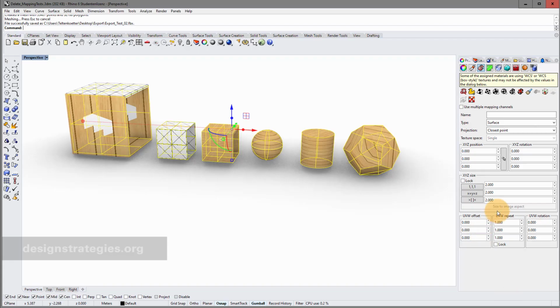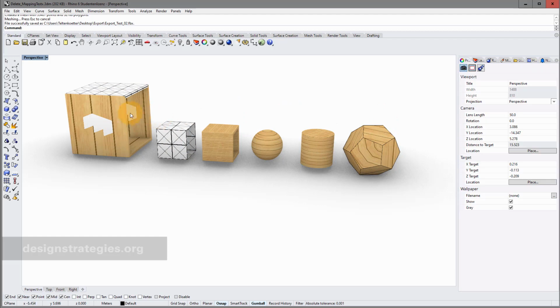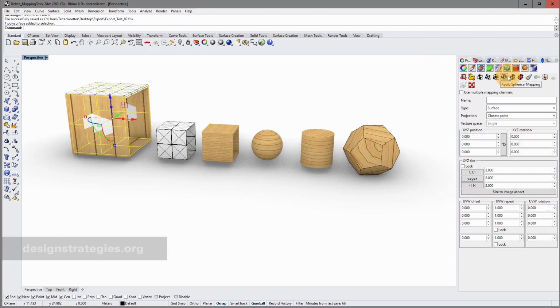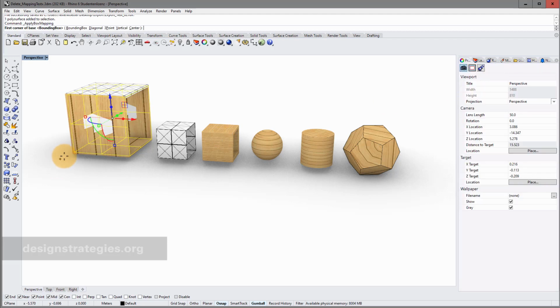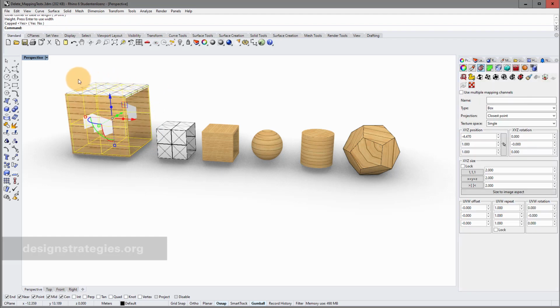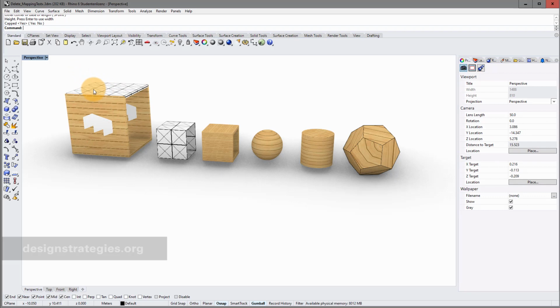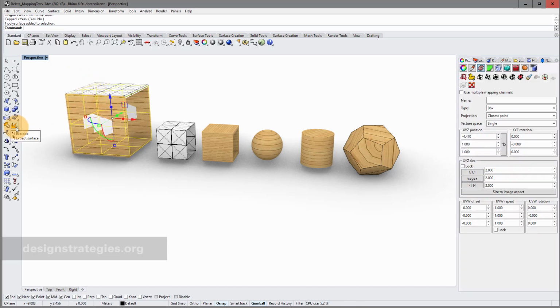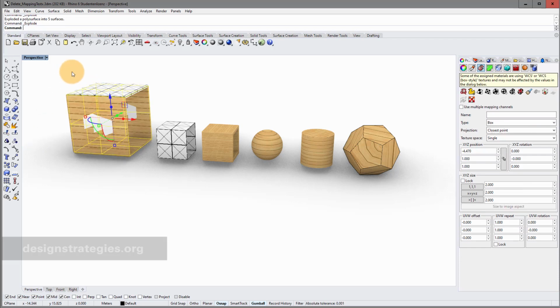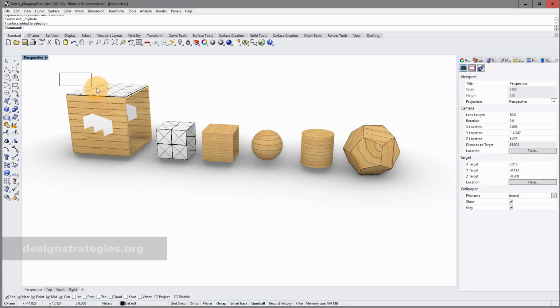So what I have to do is I want to do some changes. I just select this, and I go into my properties box mapping, and I just give this the proper bounding box. Select this one and then go up and say cap yes. The next thing I do is I just select all objects, and I just say explode, because when I explode these surfaces you can just see that it kept the texture, but then I have the chance that I can see the whole thing also in Twinmotion like this.